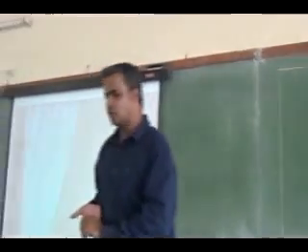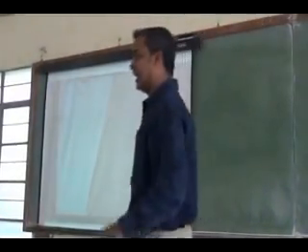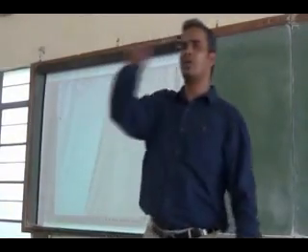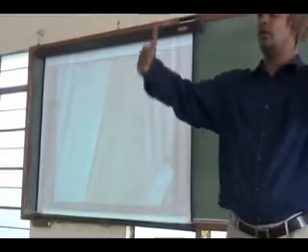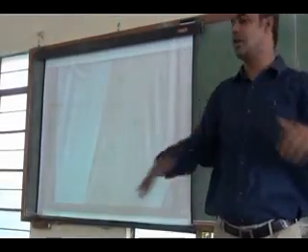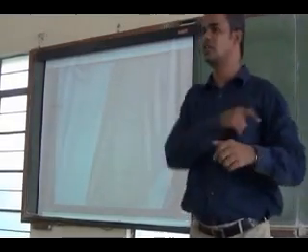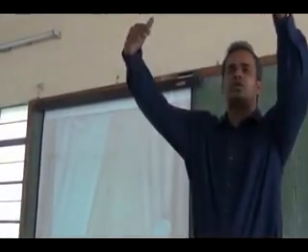Now what you are going to do: move your drafter's horizontal scale and align it to the top layout line you have drawn. That layout line you drew manually is going to be your reference. That's why you have to fix your drawing sheet carefully in a perfect manner. The horizontal scale is the lengthiest scale. Move it to the top layout line, align it, and fix the knob.